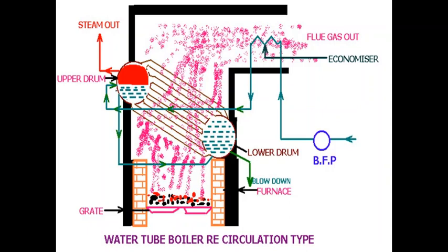There is a provision of piping which is outside the furnace and connected to the lower drum, the mud drum. So there was an introduction of the downcomer arrangement. This way a natural circulation system was developed, along with an arrangement to remove the sludge due to this recirculation through blowdown, and steam taken out from the upper drum at saturated condition.